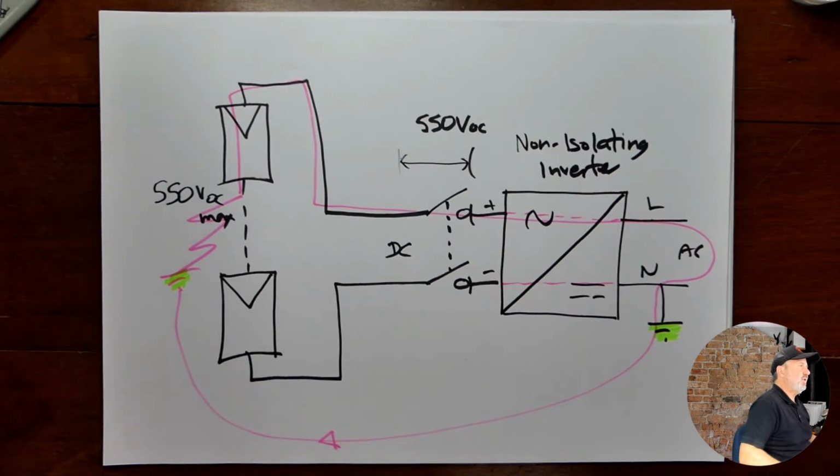So let me just jump back here. There we go. So that's a little overview of some of the things to consider when you're installing a PV array. I took you up to the DC terminals of the inverter, or the power conditioning equipment, to use the terminology in the standard. What I'd like to do is go beyond the inverter next week and cover off on the AC side of the standard, which is 4777. Part 1 is the installation standard. And it's a joint standard with Australia and New Zealand, so it's equally applicable to both countries.